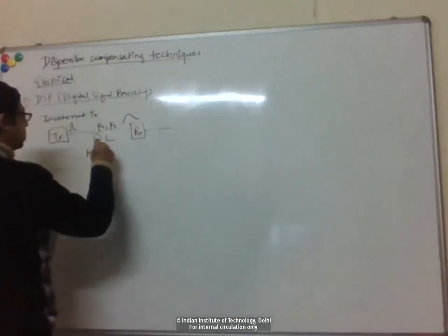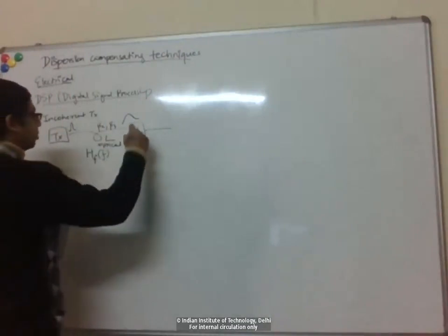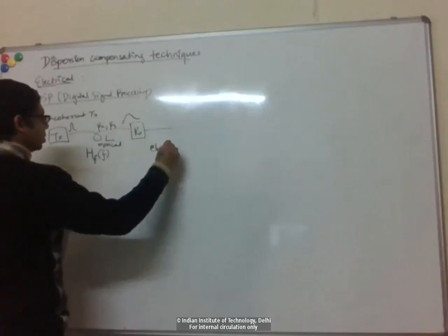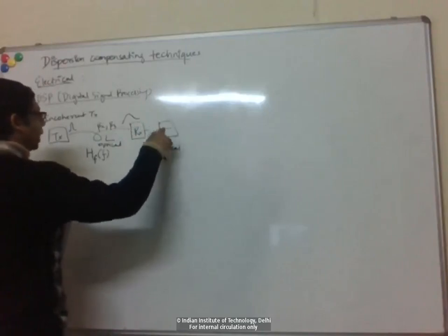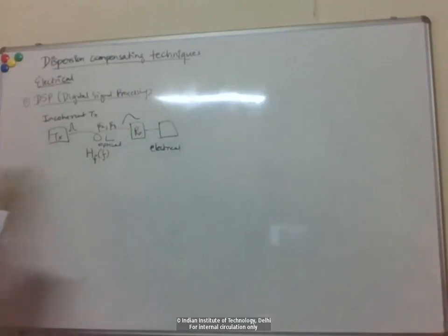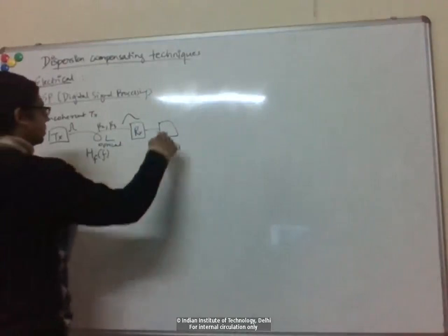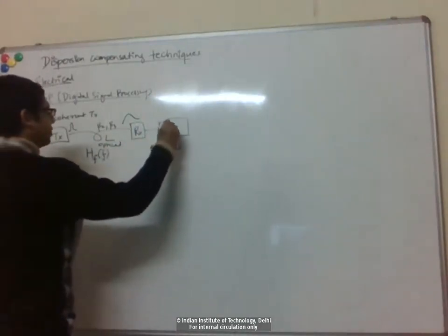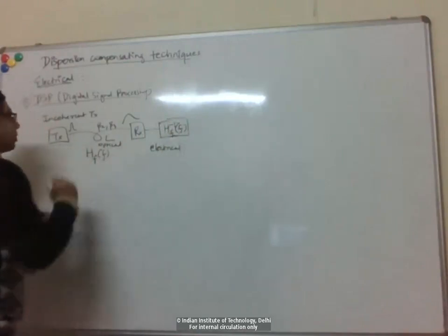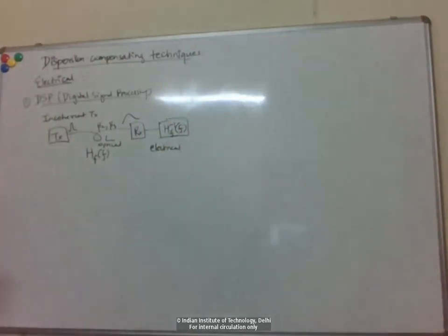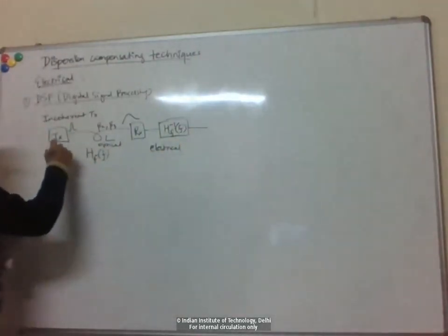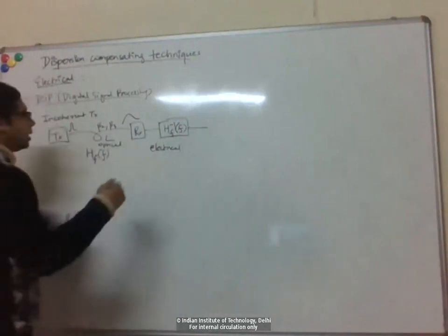So here this is optical in the fiber. Once you photo detect, now you're back to the electrical domain, and now I can try to use some electronic filtering or signal processing techniques. For example, the simplest thing you can imagine is if I have a filter here which is the inverse of the fiber response, then I get back what my transmitted thing was.